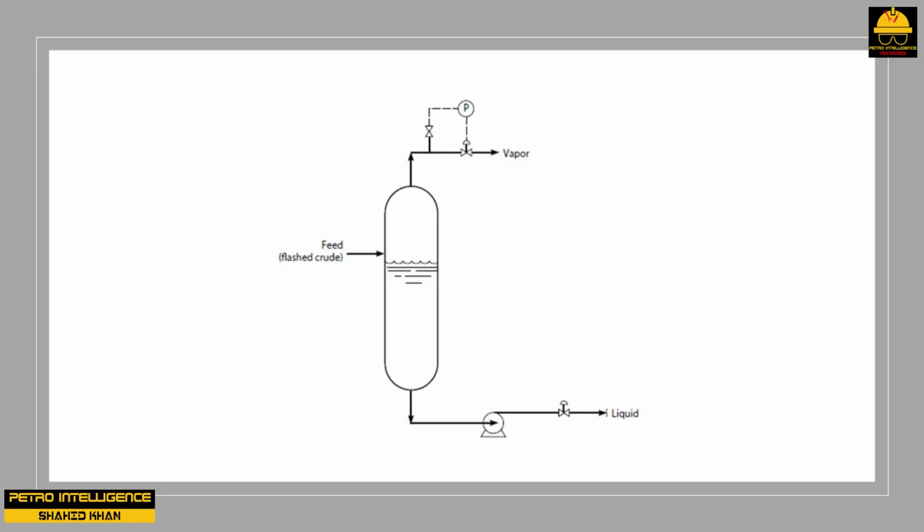Temporary solution: increase in NPSH. This pump is presumed to run fine once it is running. The available NPSH is such that it exceeds the running NPSH. So how can he provide a temporary increase in the available NPSH to satisfy the temporary starting NPSH requirement? The answer is to suddenly increase the pressure in the drum by partly closing the back pressure control valve shown in the picture. This will instantly increase the pressure at the suction of the pump.